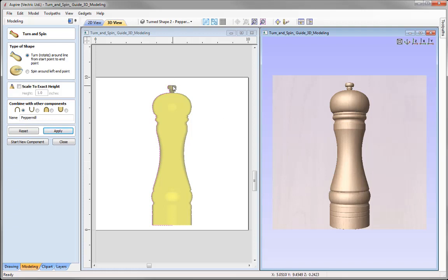So remember, we have this imaginary line that runs from start point to end point. So where the vector is closer to that line, we're going to get less height. So if I run my cursor over this point here, you can see highlighted there, it's just under 0.3. And then where the vector comes further apart, like here from this imaginary line that runs through roughly around here, and if I hover over the actual component, you can see we're creating more height. That's at around 1.2. So the closer it is to that line, the less height we have, the further apart, the more height we have.